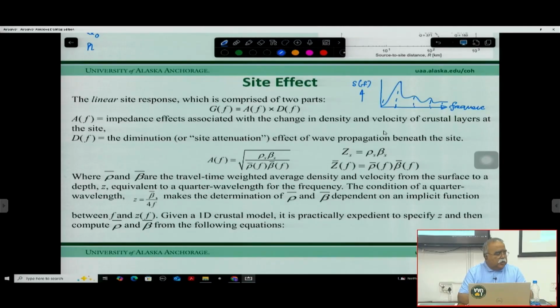In most strong motion studies or network studies of the data, we always calculate these things from the recorded earthquakes. From the recorded earthquake, by our routine analysis, we always calculate the site response value of that particular site where the recording is being done. So if that data is available, that means with frequency you know the site values, then you can directly use that, right?